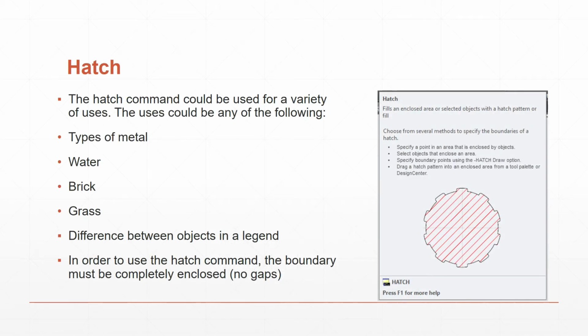And with all those sections, once again, we're going to use the hatch pattern. The hatch is a real easy thing to do. The only stipulation you're going to find is that you can't have any gaps when you use the hatch command. It's going to be used to enclose that object, and as long as it has no gaps in it, you'll have no problem using the hatch command. It will tell you sometimes if you do have a gap, and it usually puts a round circle or something of that nature and lets you know where that problem is.